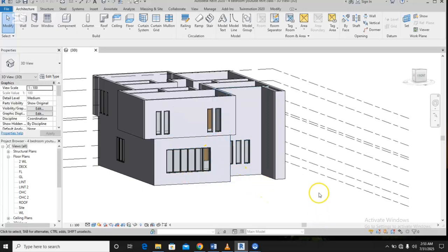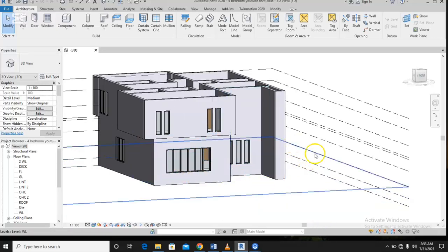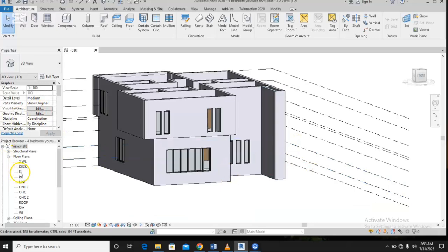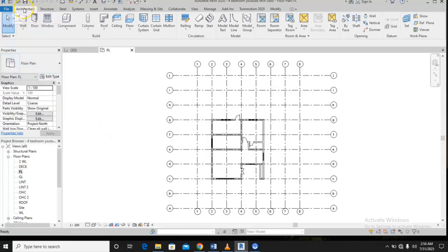So we're going to be setting up our floor level, then our decking level. To go into our floor level, the first thing you do is click on the floor level here. After clicking on the floor level, we'll move down to architecture here, and then down at the properties bar we have the floor here. We have different types of floor: architectural, structural by phase, and all these things. We'll dive in small, but today we are going to floor architecture.